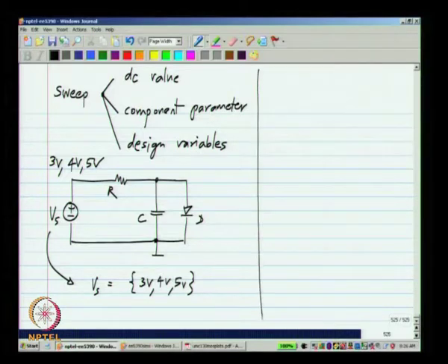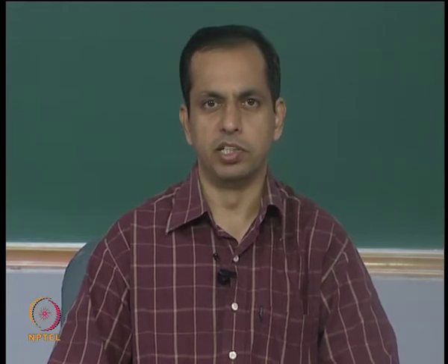And in addition to these things, there are a number of other more sophisticated analyses, such as periodic steady state and others which are suitable for specific circuits. There are a number of circuits that operate with periodic inputs and attain a periodic steady state. For that, the periodic steady state analysis is useful. So, again, these do not fall under the basic analysis and we will not read them here, but you can look at the simulator's manual and the extensive information that comes with it to find out about these things.